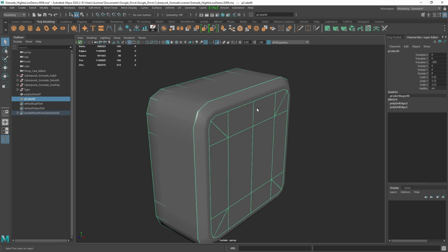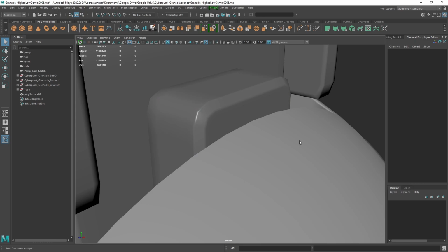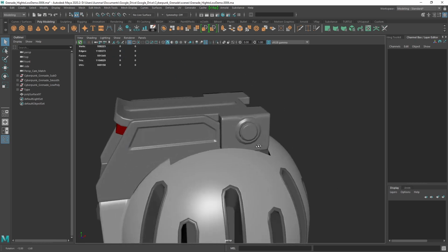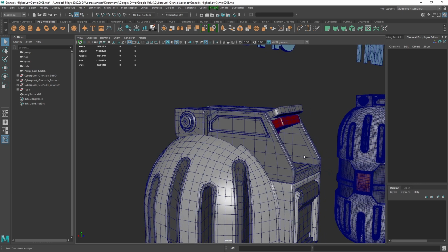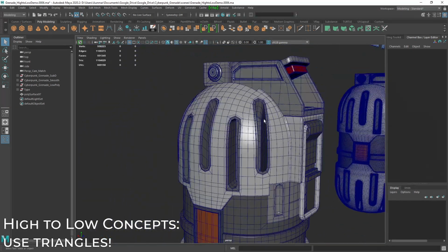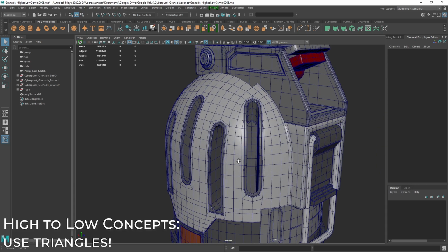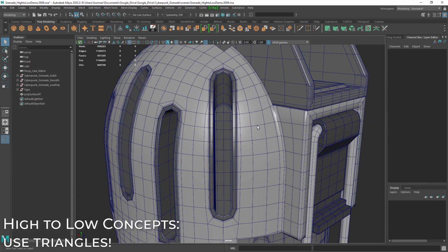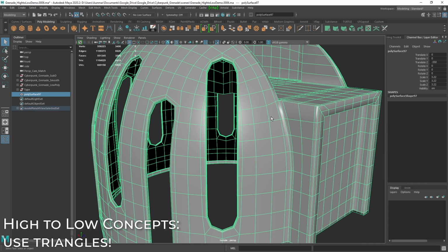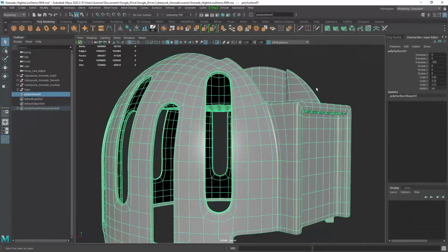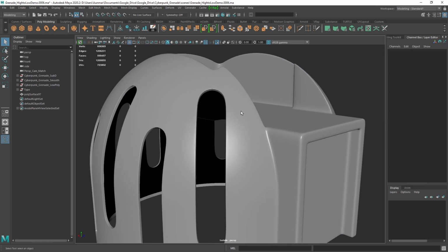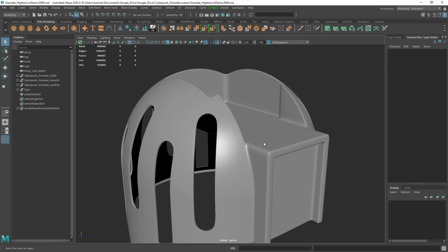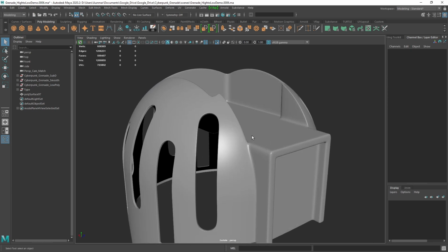All right, so the next concept I wanted to bring up, especially when doing optimization, is that triangles are completely fine. So when I'm doing sub-D modeling even, having an occasional triangle is completely fine, right? And there were a couple of joke comments about how it was blasphemous and they can't believe that, or they spent a big part of their career making sure that they never had triangles. So did I, you guys. It's not a big deal, right?